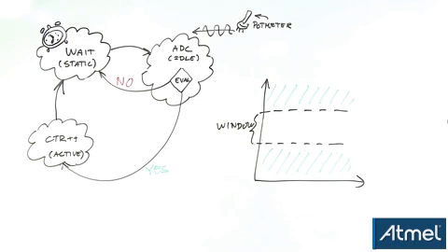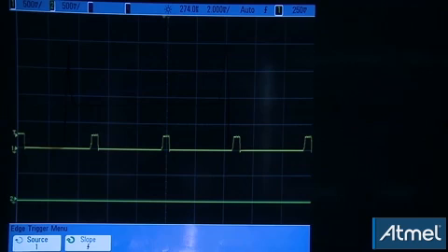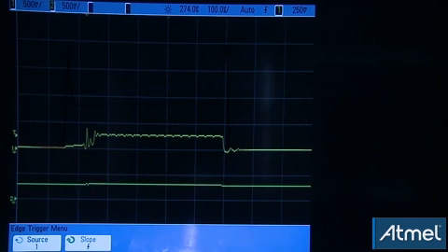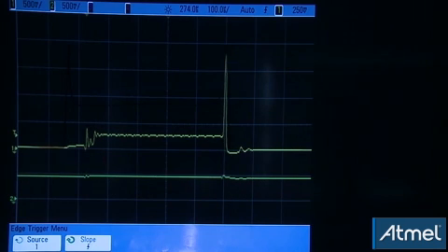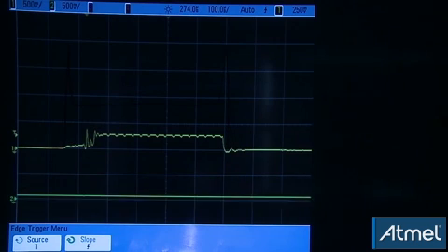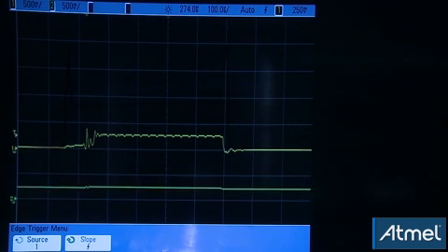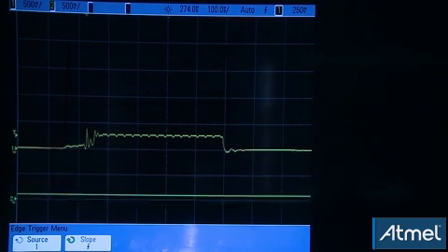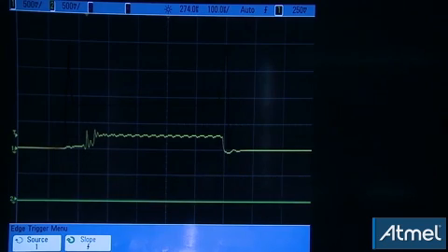Now let's take out the oscilloscope once again. This time it's different. Watch when you go above the threshold. Near the end of the pulse, the CPU is activated for the processing, and this peak is the same height as for the classic mode. Of course, our processing in this case is just incrementing a counter, but the point is proved. Sleepwalking saves power. Let's have a look at how much we save.